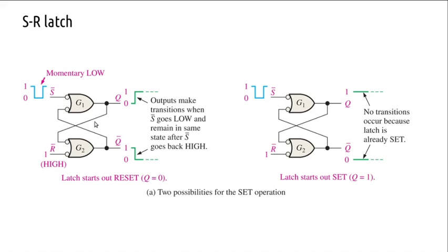So this is 1 and 1 and 1, that is NANDed, that is going to be 0, and 0 is again 1 and 1, that is NANDed. It is not the reset condition, so the feedback is taken from here. This will go from this direction. So this is 1 and 1.